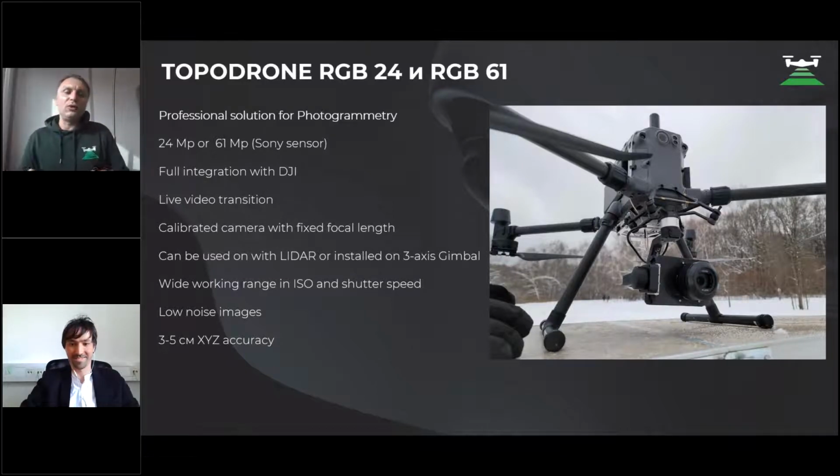You know that a survey with the LiDAR has a very huge coverage, and common photogrammetric cameras like the P1 have a very small field of view, and it's not so productive to use the P1 camera together with the LiDAR, because you need to provide bigger overlapping if you are using a camera together with the LiDAR.